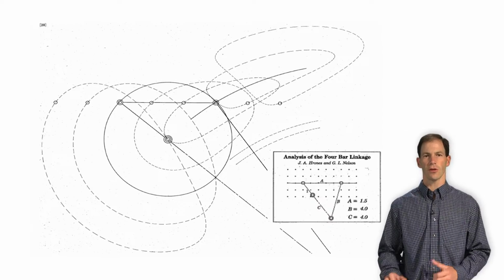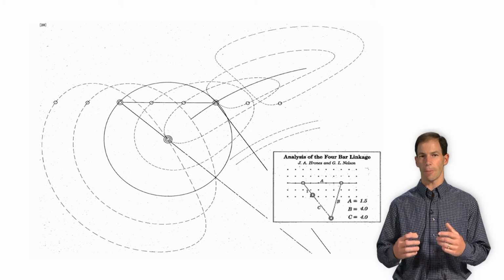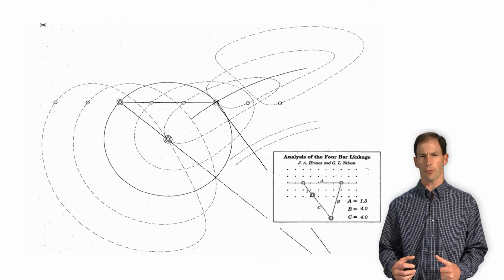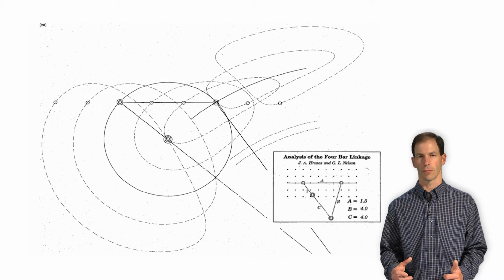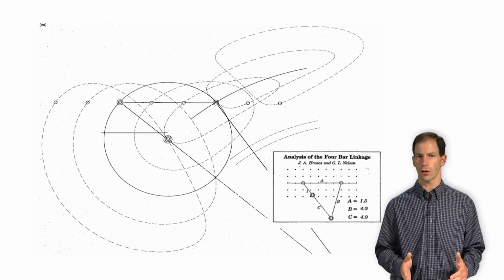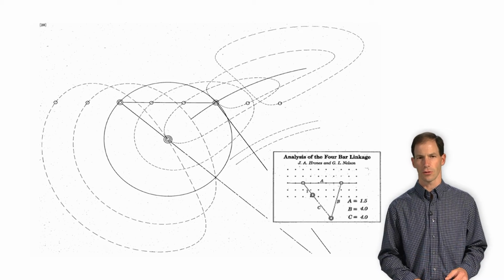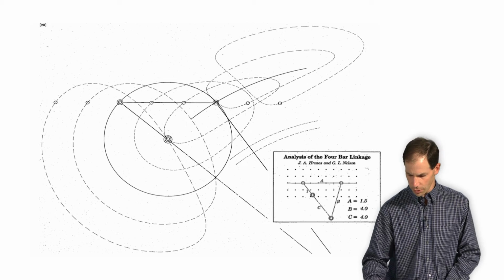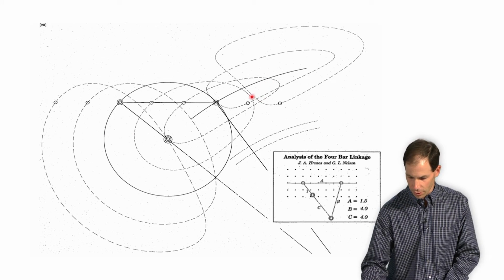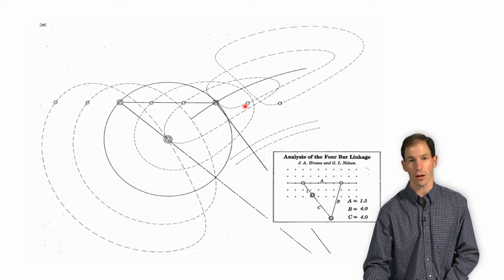All right, so here's a page out of that Rones and Nelson Atlas that I happen to pull out, thinking that this does a pretty good job of approximating the motion that I wanted for this painting mechanism. You might say, well, didn't you want this vertical line relative to where you were dipping into the painting mechanism? Well, let me propose that this is the approximate straight line of the wall, and all I need to do is rotate my mechanism a little bit.